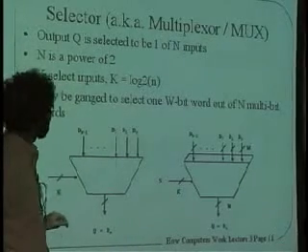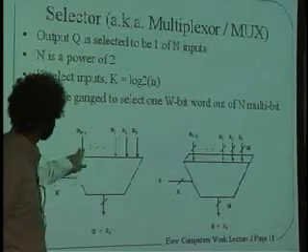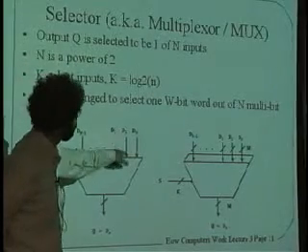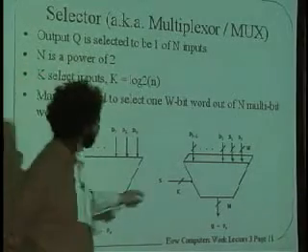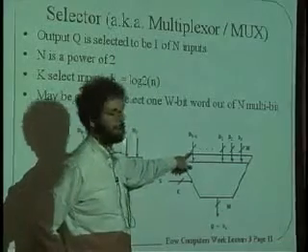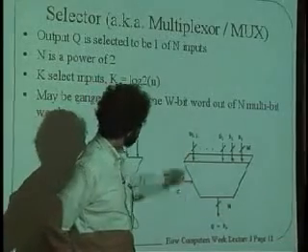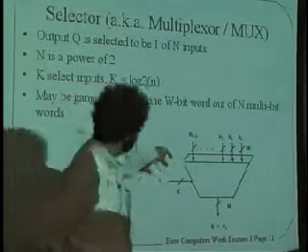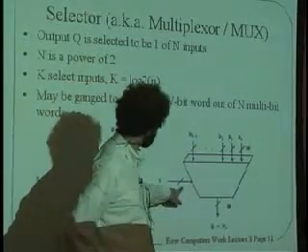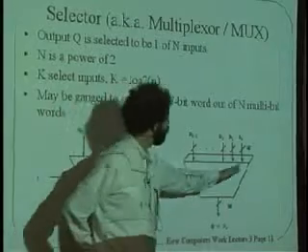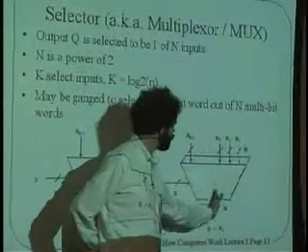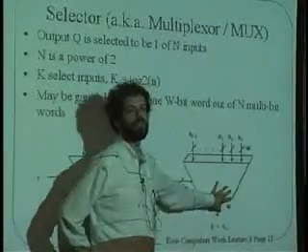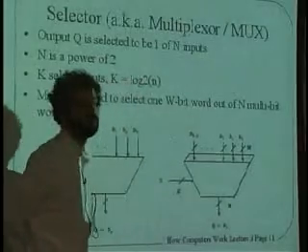Now, of course, this is shown here with only one bit going into each of the inputs, but in fact you can have a wider number of bits, perhaps 32, and that's shown by the multiplexer being thick here. When you set a particular selection, all 32 bits will be chosen to pass out to here. And in general, this is the kind of selector that we're going to use.